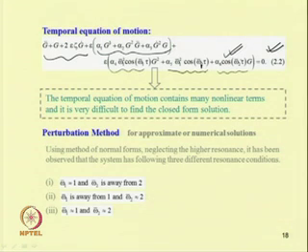It may be noted that a part of the axial loading, that is the static force, will be the coefficient of the g term, that is the stiffness term. So, the stiffness of the system, and hence the natural frequency, will be affected by the static part of the axial loading and by the dynamic part of the axial loading.